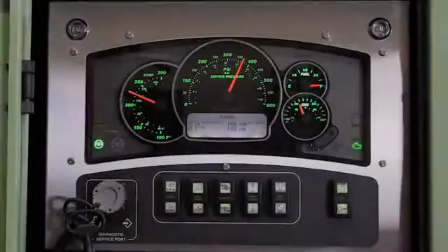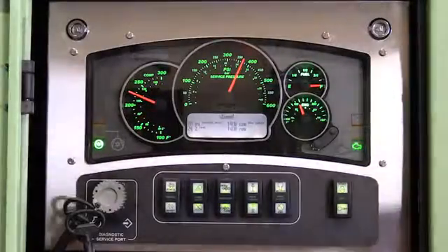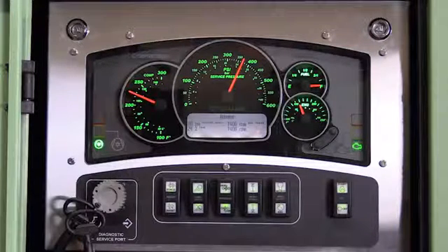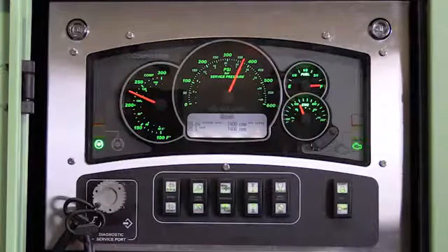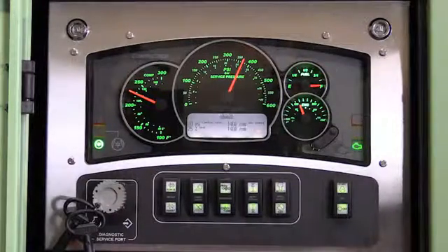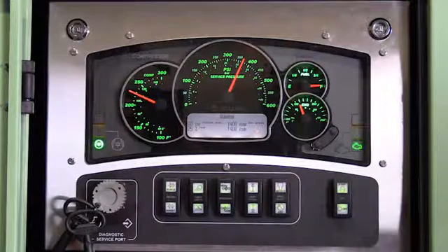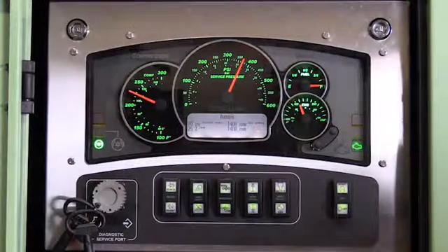Here we're going to demonstrate the exhaust regeneration procedure. The aftertreatment constantly monitors the soot levels of the exhaust gas. If the soot levels detected by the indicator reach above 80%, the engine electronic control module lights the DPF lamp on the controller screen and should automatically trigger the ARD to ignite diesel fuel passing through the DPF until soot levels return to normal, less than 10%.